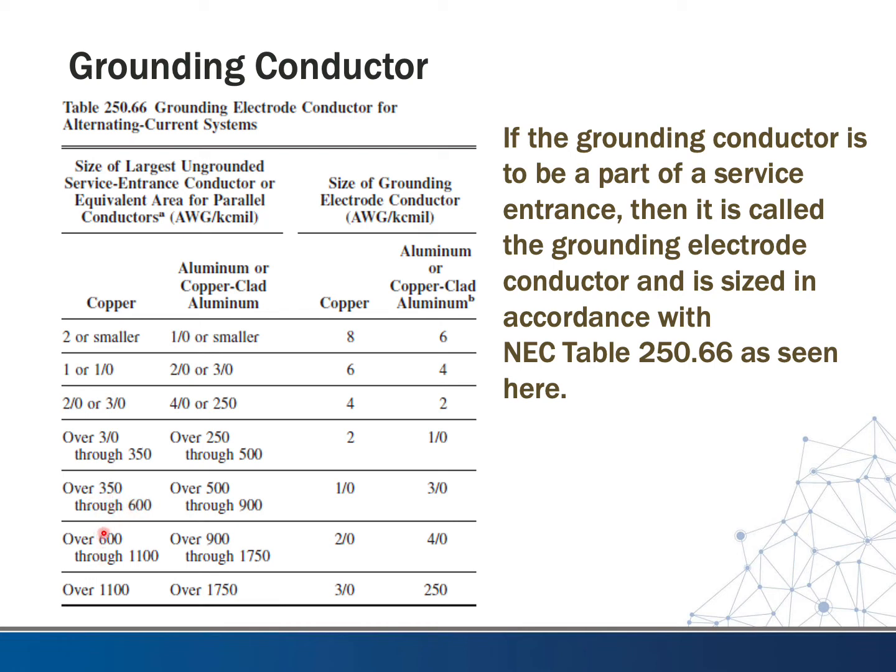So you have to take the total cross-sectional area, you have to take the total area there. But once you get above this size, 3/0's the largest grounding electrode conductor you'd ever need. You don't have to use larger than that. So that's an interesting aspect there to think of. Now, many times we'll oversize that or continue to size it larger, but we're not required to by code.